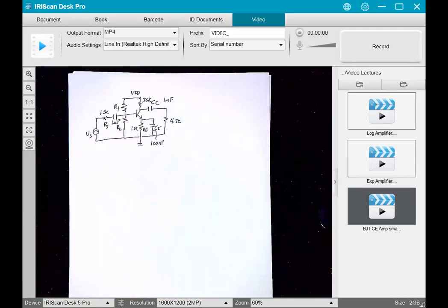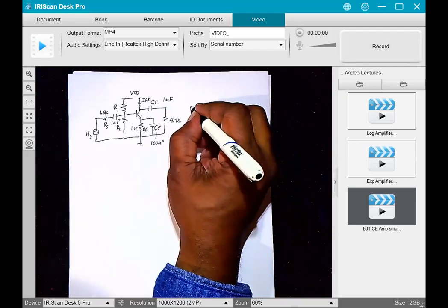So there's our circuit, with all the components. Again, it's all straight out of the textbook. What they ask us to do is determine the low cutoff frequencies, basically the three pole locations, the dominant cutoff frequency, we call it fL, and the voltage gain. We're going to assume that beta is 200.